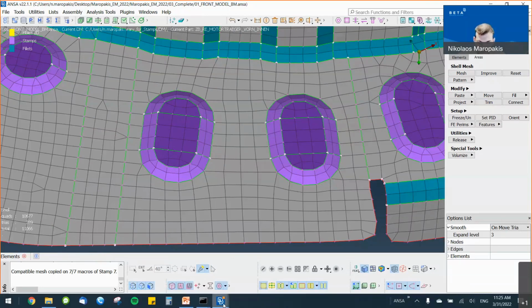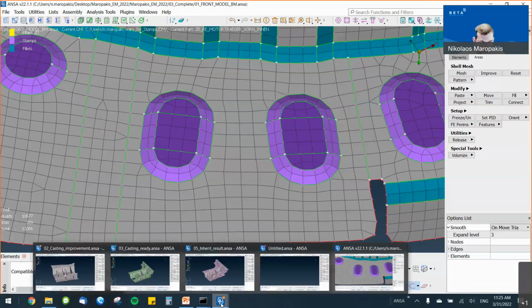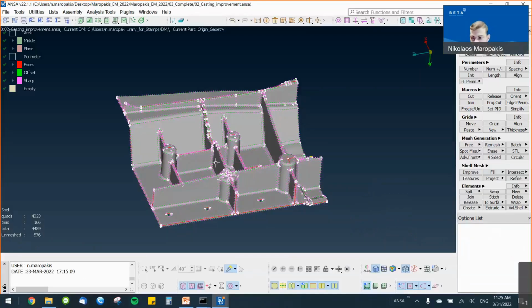Now let's move to the second topic that we will see today, the middle mesh. So similarly to the cell mesh toolset, there is a dedicated toolset for the extraction and manipulation of middle mesh from a 3D geometry. It is called middle mesh, and it can be found also from the drop-down menu from here.